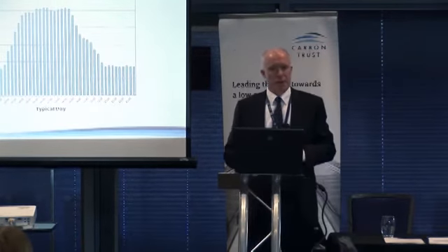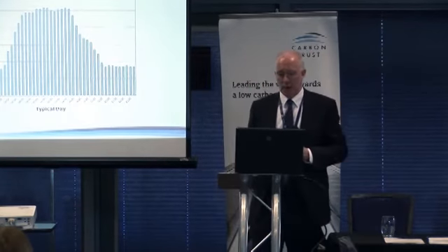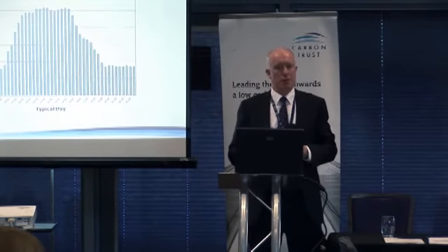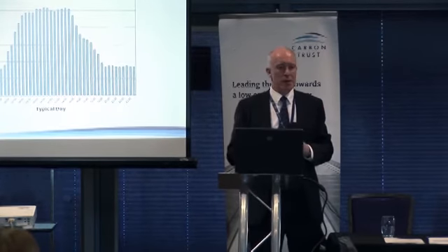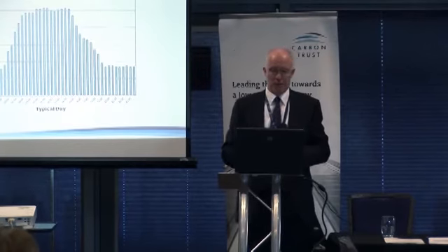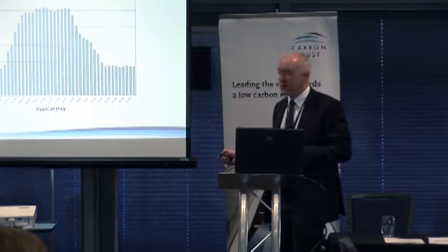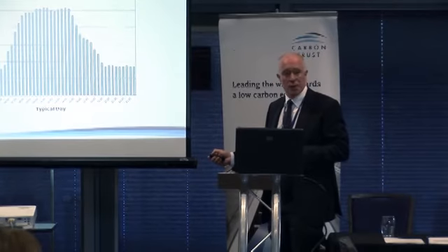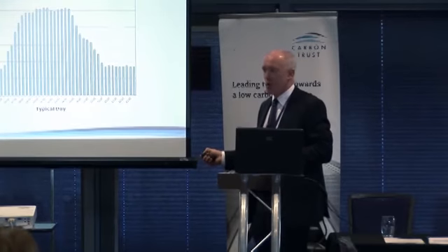Increasingly, and under the Energy Act 2011, the government have said they want smart metering to come in to all supplies, and it'll happen over a period of time. What does smart metering do? Smart metering gives you a very good way of looking at the electricity consumption throughout the day. This is the result of an electricity smart meter, and you have 48 half-hour readings from midnight to midnight, giving you the electricity consumption, what is actually consumed. So here you've got it at about 80 kilowatts. That's 80 kilowatts per half hour, or 160 kilowatts left on within the building.